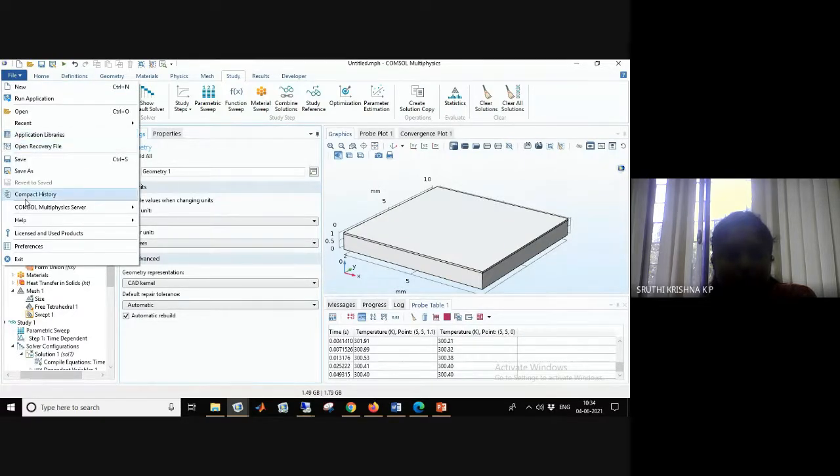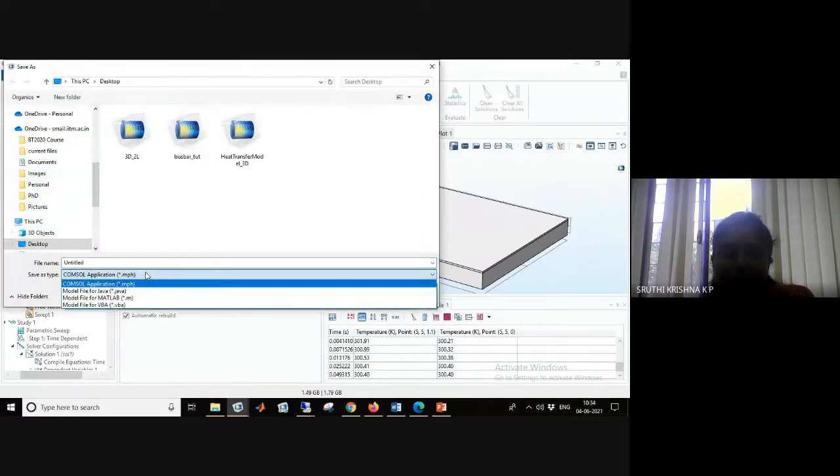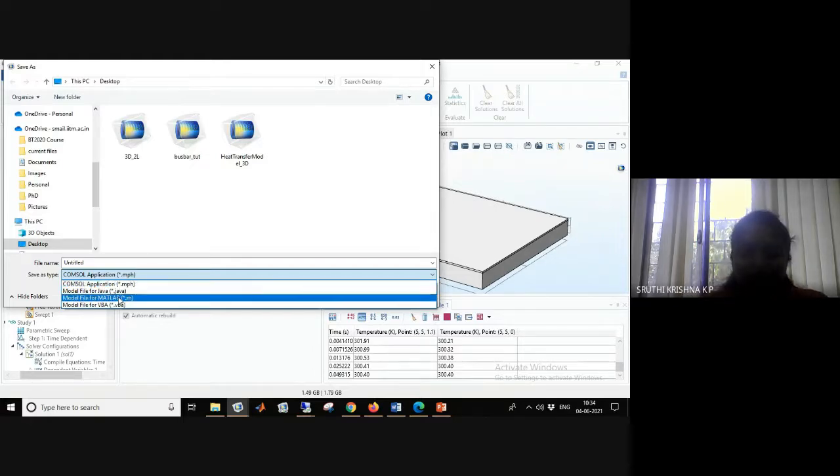Then another option is we can use it with a server also. Here we will usually save this model to MATLAB and write the code instead of changing all those values. You could do these parametrics in this model, but if you want to do a specified list or combination, you can just save the model as MATLAB code.